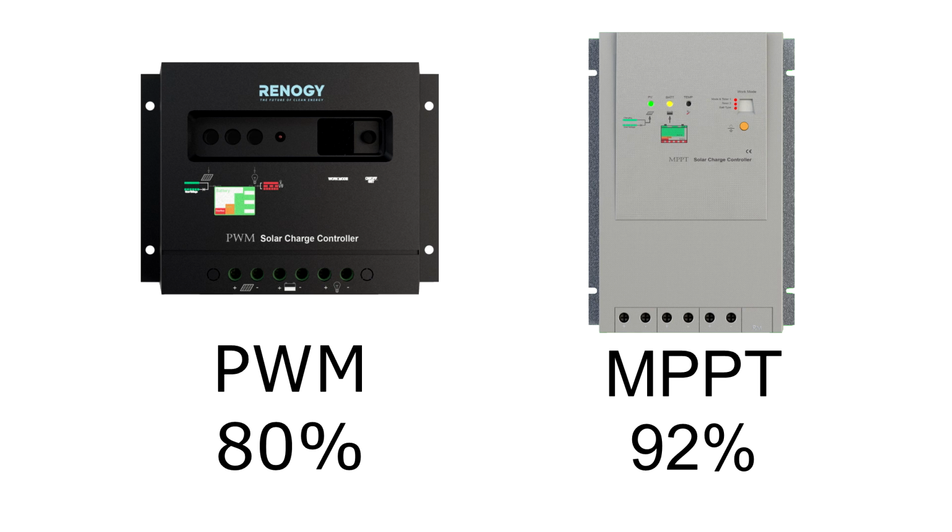Next, consider the charge controller efficiency of the system. Different charge controller types will have different efficiencies and will affect how much power you can actually draw from your system. If you are new to solar and are unsure of which controller type you wish to have, we recommend using the figure for PWM type, which is 80%. This is because typically our first-time consumer will purchase a kit with this type of controller. We recommend that you use the percentages indicated on the web page unless you know that a particular charge controller you plan on purchasing has a different efficiency.